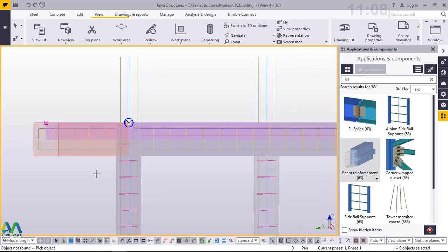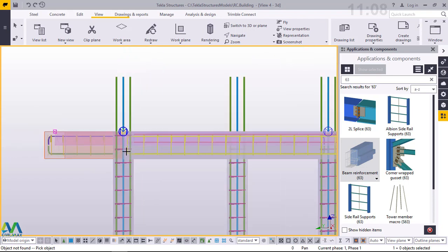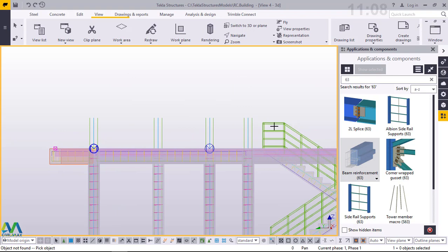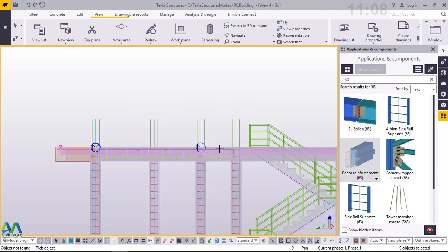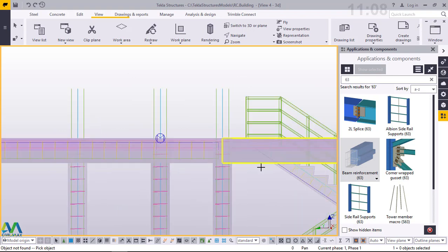So the 800 allowance of leaving starter bars is in case you want to continue with the RCC work. The starter bars are already given there. You can always extend the floors of this building using these starter bars already left or created right there.